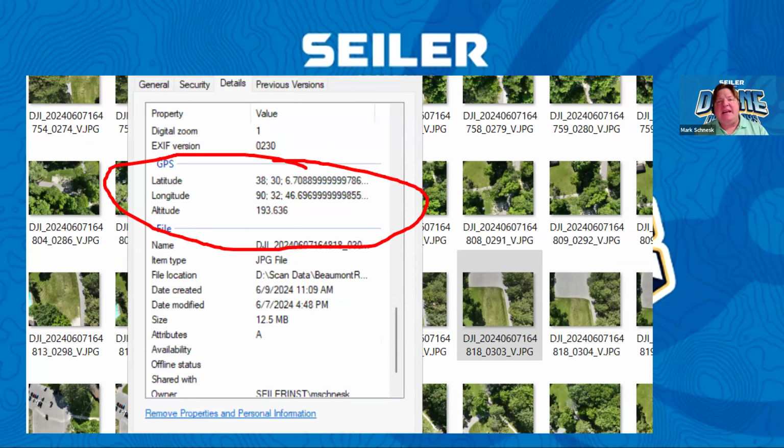It's going to post-process these together. In the case of the Mavic or the Matrice, that is real-time kinematic, so it is writing exact data to the photo. Or in the case of the Wingtra, the GeoQ, we have to have a base station, post-process that trajectory, and then assign those photo points to the photos. But either way, for each photo, it's going to write in the header, in the metadata, its position in latitude, longitude, and ellipsoid height altitude.